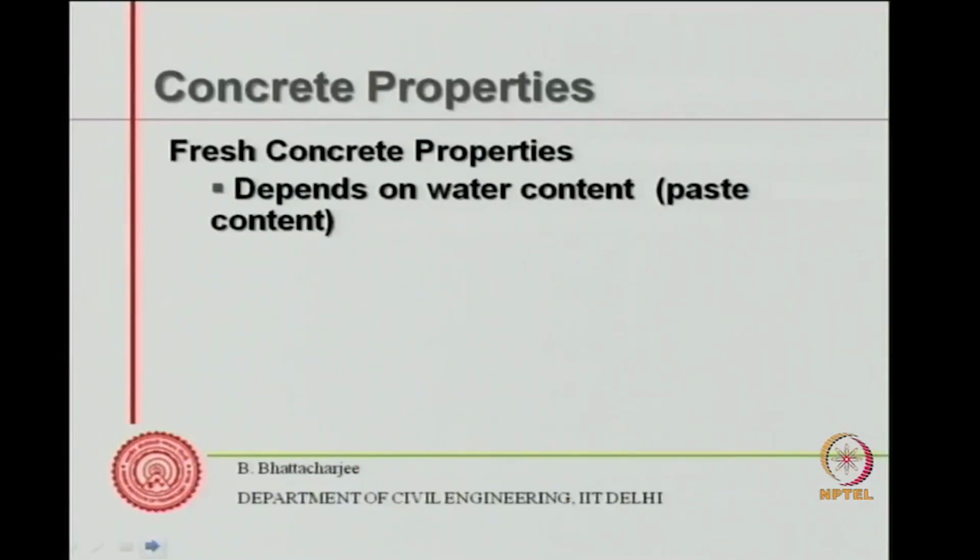How can I mold? The molding process involves essentially driving out the air from the concrete, because fresh concrete when I place it contains about 30% air voids. Normal concrete will contain around 30% air voids, and this has to be driven away. The second issue is that seldom is it placed in the final shape; it is not in the shape of the mold itself.